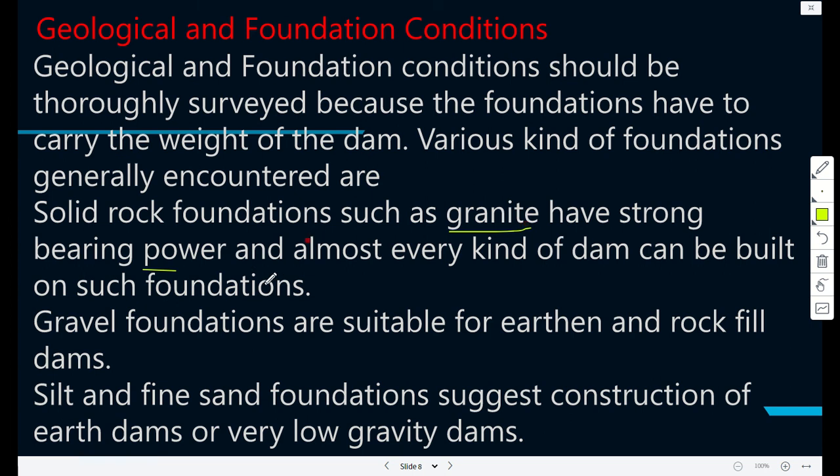rock we know. If you find that, you're very lucky, because then you can build any kind of dam on it, and there are no limitations, although of course you have to design. It's a very good foundation, I should say, and all sorts of dams can be carried. And then gravel foundations are suitable for earth and rock fill dams. Silt and fine sand foundations suggest construction of earth dams or very low gravity dams.